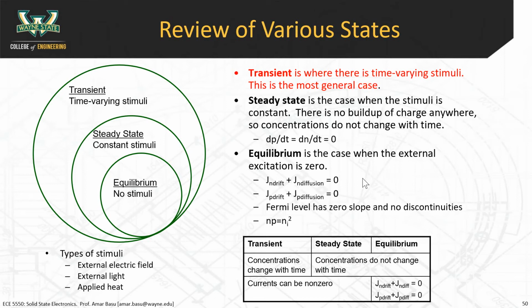Where was I going with that? Oh, so that works on a different principle, but the way fiber optic communications work at a very, very basic level is that you have a fiber optic cable. On one end, you have a transmitter, like a blinking laser or a blinking LED, light emitting diode. Blinking means you're sending ones and zeros across the line. That's how you send information. And on the other end, you have a receiver. The receiver is usually a photodiode.